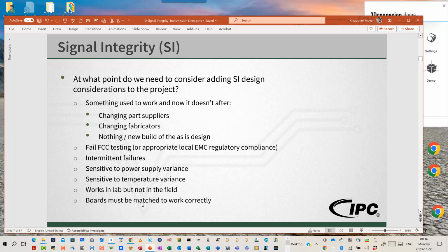This actually, one of my very, very first jobs back circa 1992, 93 time frame, early 1990s. I was working at this company in Michigan, and they literally had this process. They thought it was just fine, where when they'd get a batch of new boards in for the product, they'd literally go through and have a batch of the processor boards and a batch of the sensor boards. And they would have a technician take a processor board, plug a sensor board in. Does the system work? No. Get a different sensor board. And you'd keep matching them until you had a matched pair that said these two boards work together. This is one system. And that says your design is so marginal, right?